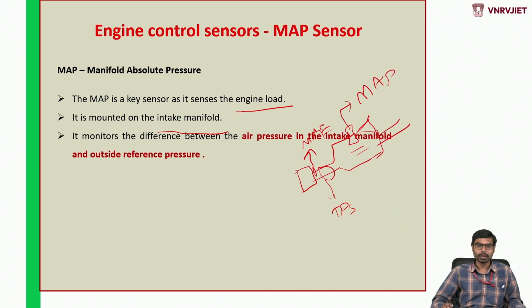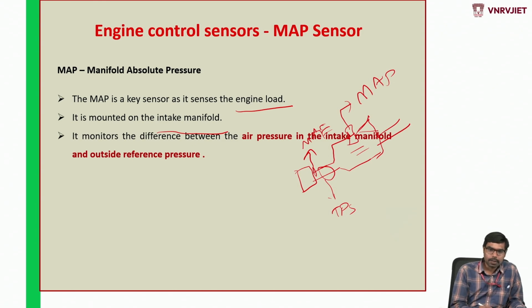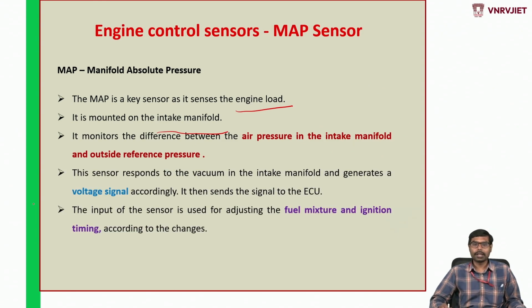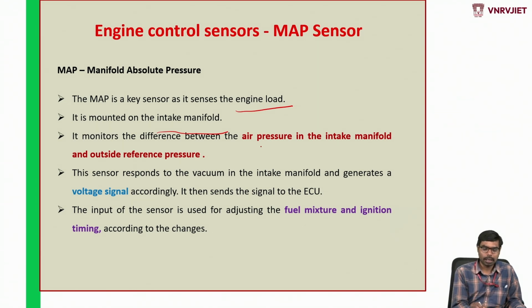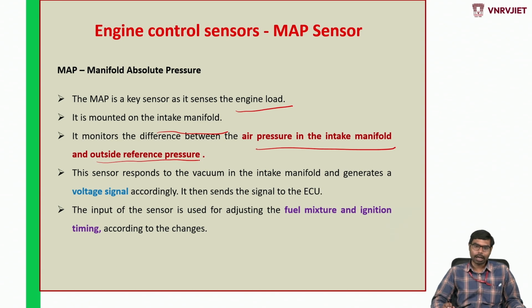It monitors the pressure in the intake manifold and the outside reference pressure, as I already mentioned. Due to the pressure differential between the outside atmospheric air and the intake manifold pressure, the vacuum pressure, which is present inside initially, the outside atmospheric air enters into the engine.